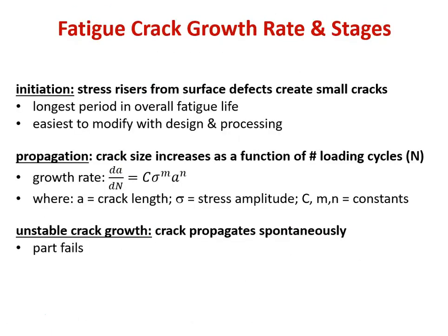Okay. Fatigue crack growth rate and stages. Fatigue cracks do not grow at the same rate during their entire lifetime. Most of the time that is spent in initiating, propagating, and growing a crack is actually spent initiating it.